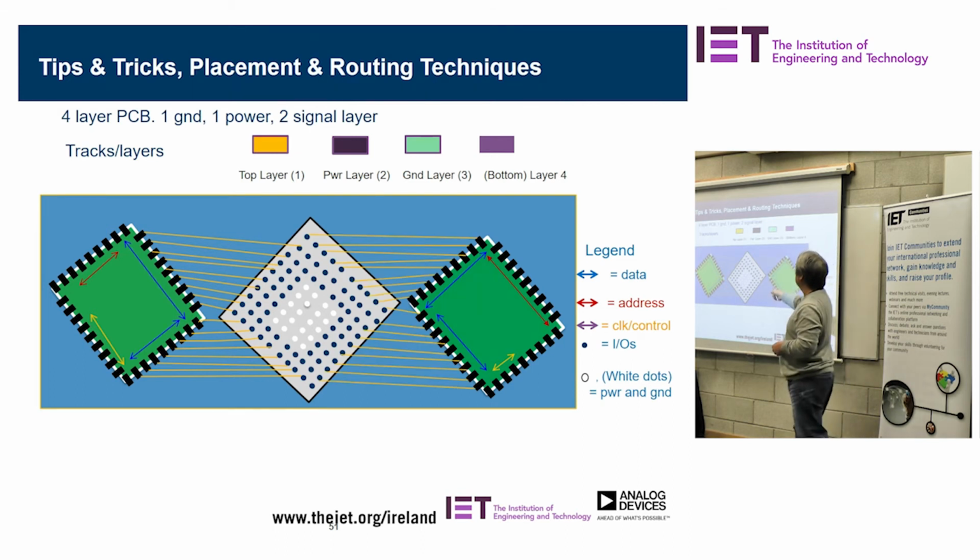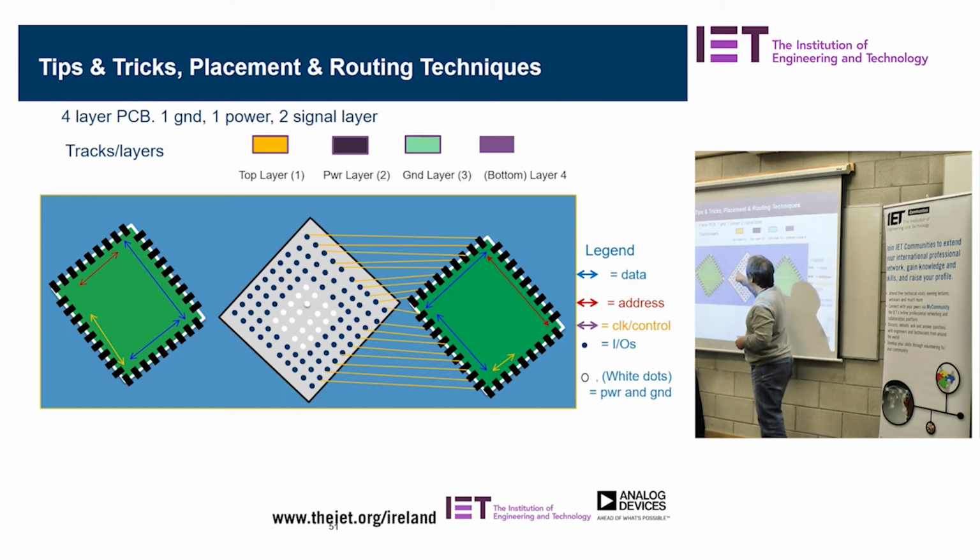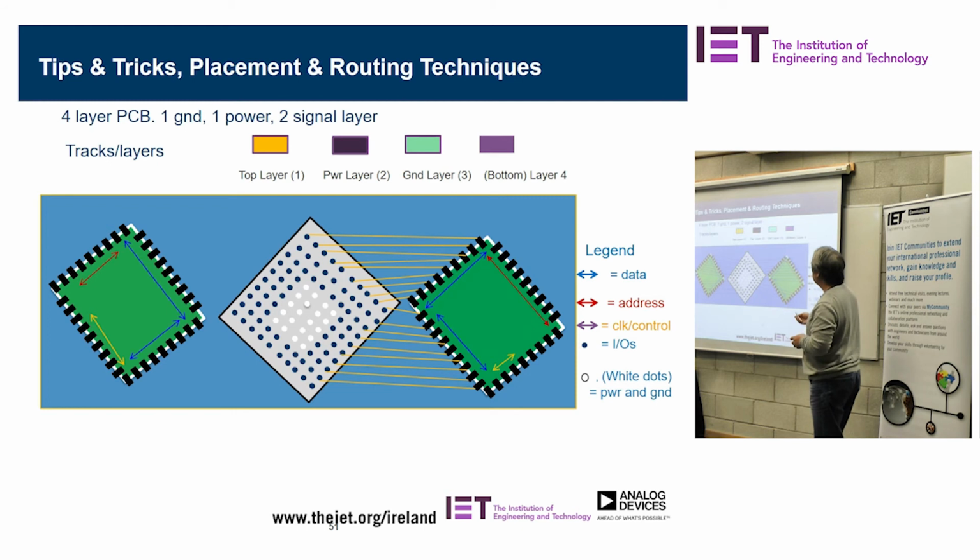On the other side, in other words the outer layer, even though it goes down, you route it across from the top layer. So you route it from the top layer on this guy, right? So I'll take out the other one for clarity. And the second layer, which is the second pin, you go down to the other side, across and up. So there's no crossing of the wiring and routing. So it makes it very efficient, short and sweet.